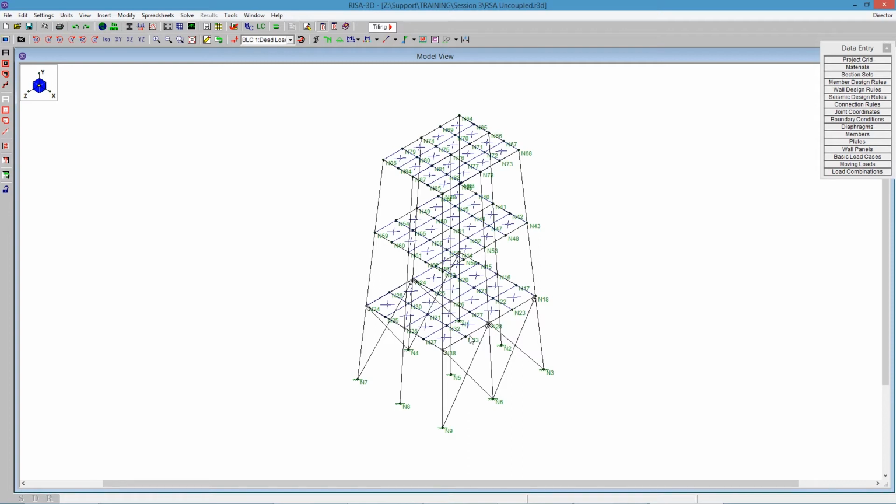Different parts of the structure are going to be activated at different natural periods, so there may not be a single natural frequency in the structure. This is what makes the dynamic analysis so valuable, is that you can take the natural frequencies of each portion of the structure and combine them to get an overall dynamic response. And that's what ASCE 7 is requiring.